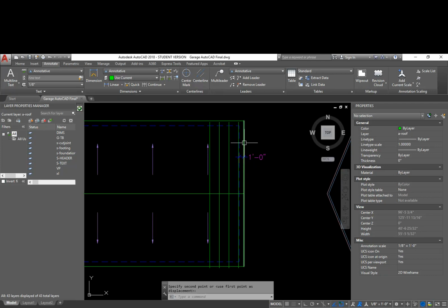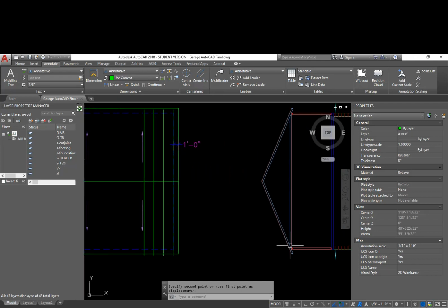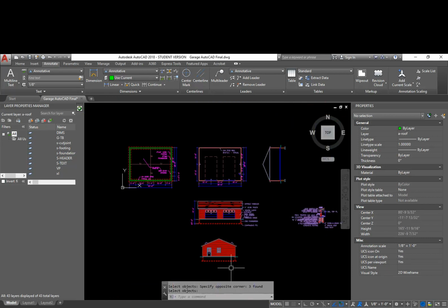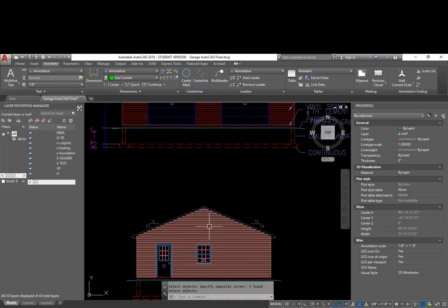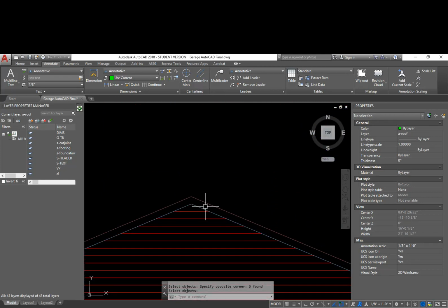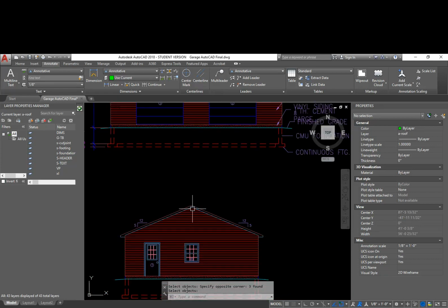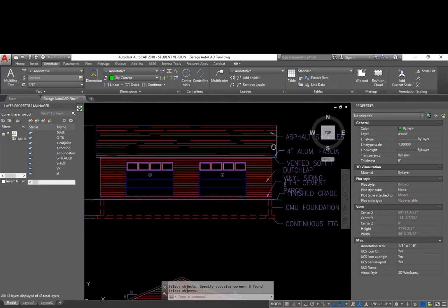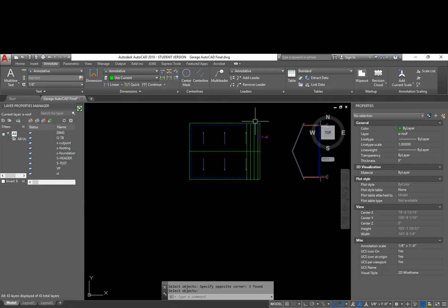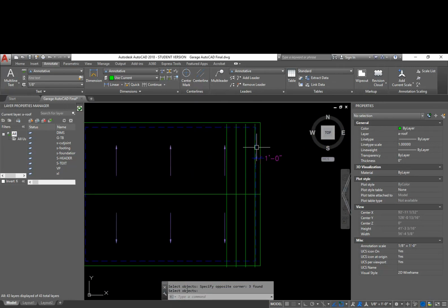This out here cannot be a regular truss because, first of all, there's nothing for it to bear its weight on. And second of all, I don't want to see the bottom chord of the truss out here. I want to see an end that looks something like this, with the siding running the whole way up to the underside of the fascia. So this is called a rake. We call this a rake, and it's basically an extension of these trusses, or the top chord of the trusses.